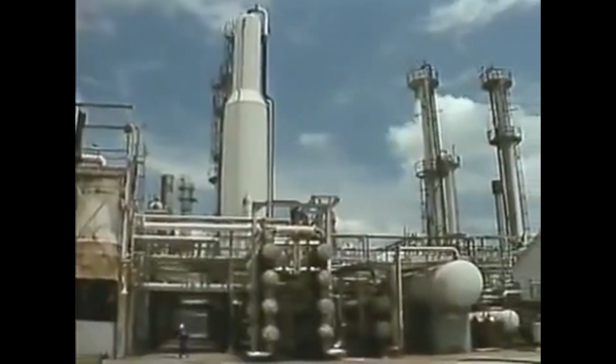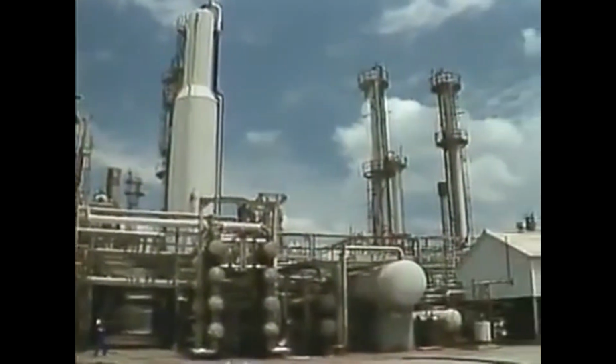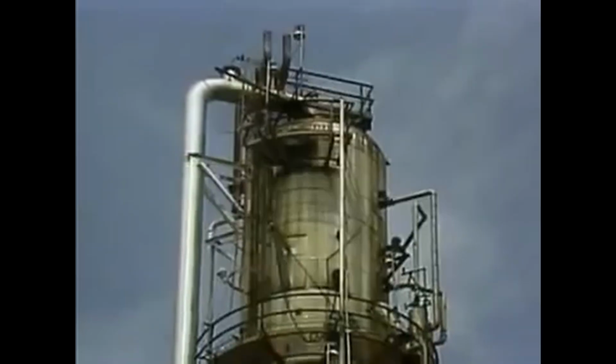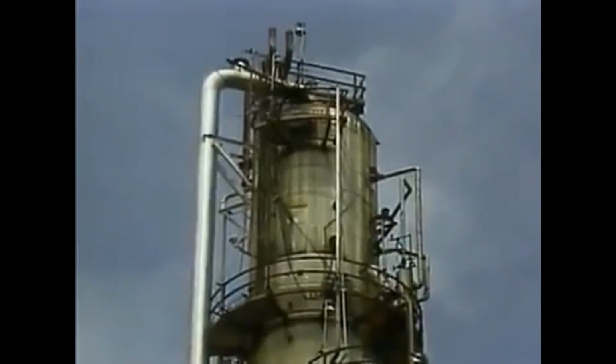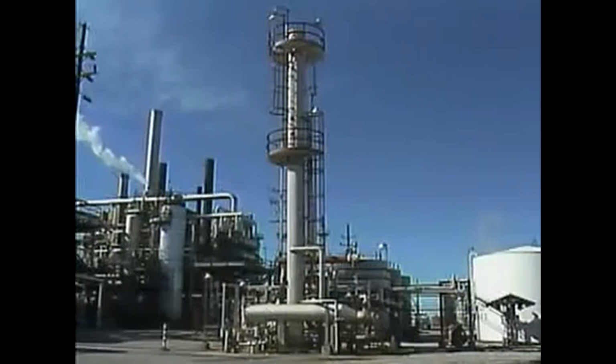One of the key elements of many process plants is a distillation system. It's important for operators to understand how distillation systems work because it's part of their job to make sure the systems run properly. The purpose of any distillation system is to separate a liquid mixture into two or more components. The separation takes place in a distillation column or tower. The liquid mixture is called feed or charge, and the components into which it's separated are called cuts or fractions.